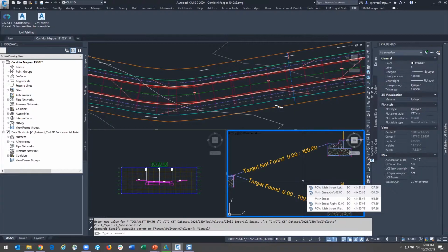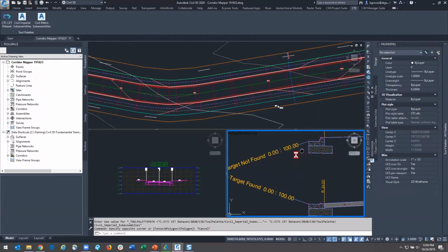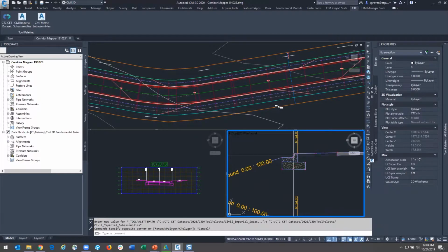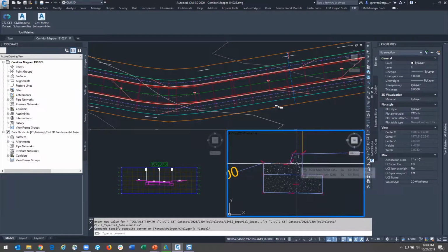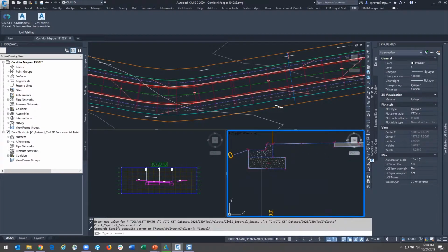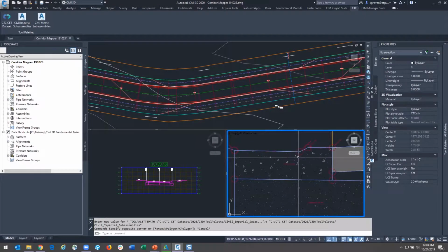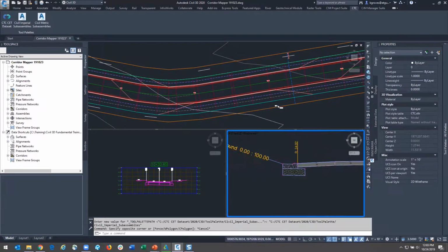But eventually, cars are going to want to turn off of the main travelway and go into some sort of side travelway. And so with that, we're going to have barrier curb, 6-inch, 9-inch, whatever. We're going to have barrier curb for a situation where we're in the main roadway. And we're going to have a mountable curb in an area where we're going to, well, mount our vehicle and drive over top of that.